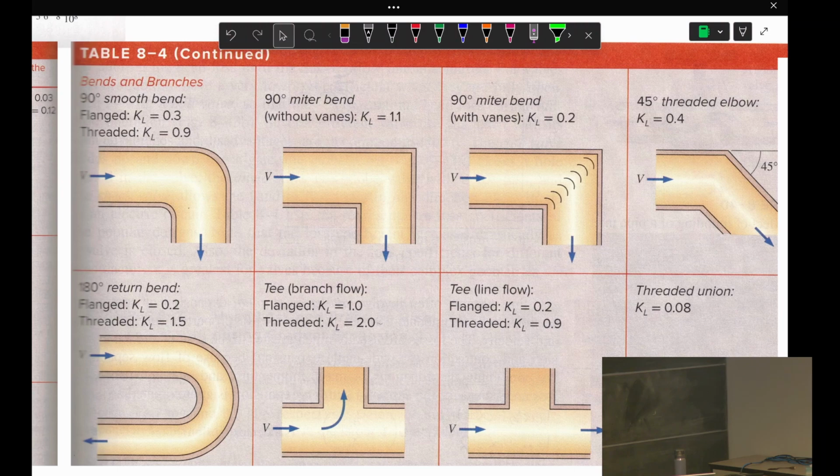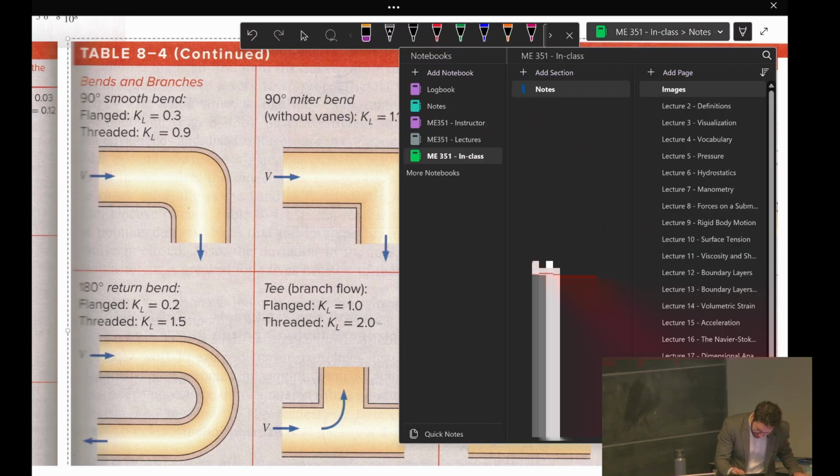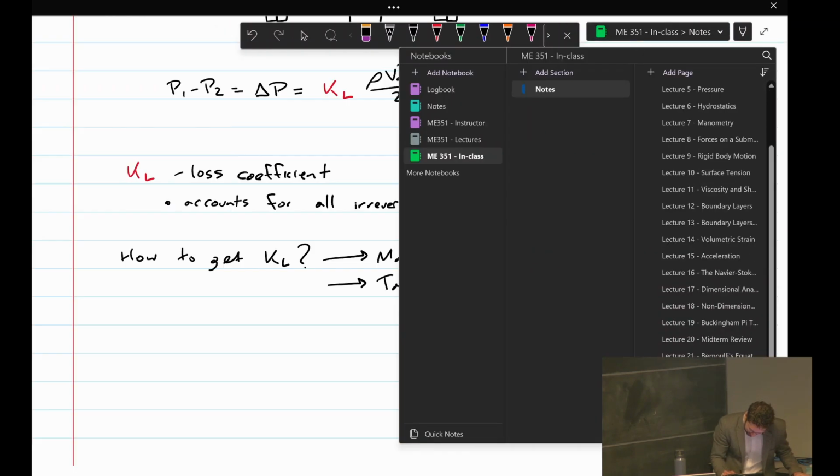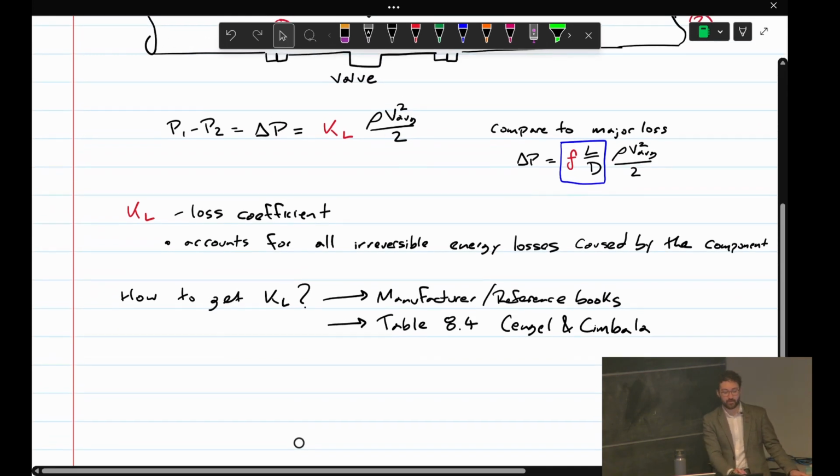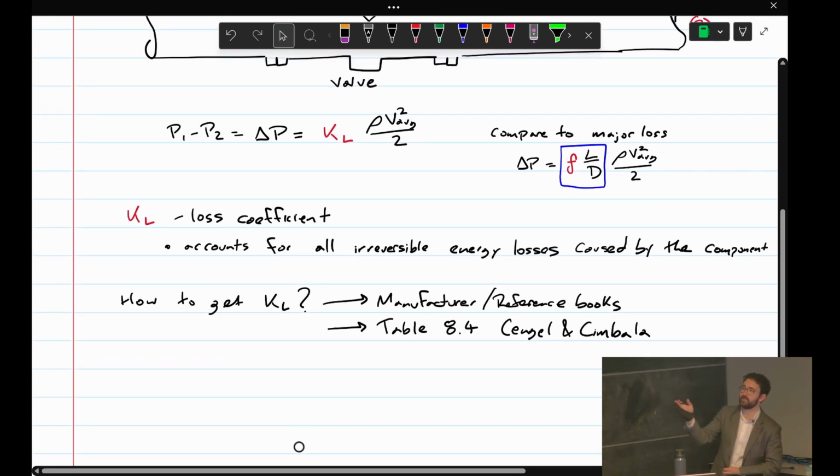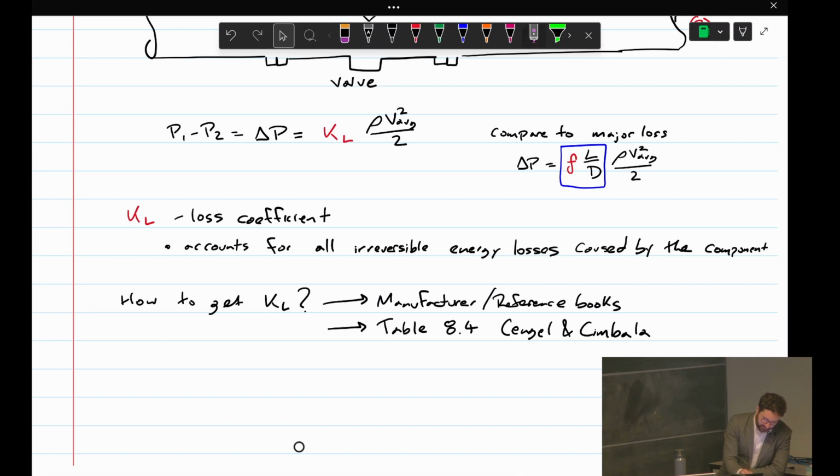Yep. Let's say you don't know the parameters. If you put just a valve into CFD, can you extrapolate that from the data? Definitely. This loss coefficient is how the manufacturers provide this too. So if you end up working in valve manufacturing or some sort of shop that produces these components, you might be working on design to basically reduce KL.